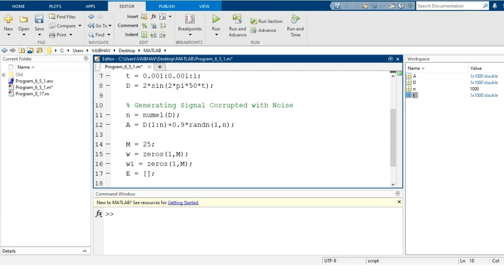And as we have seen the update equation of the LMS algorithm, it has on the RHS the second term there, one constant that is called mu, which is representing the step size here. So here we can keep, for convergence purpose, the value of this step size to be very, very small. So we have 0.0005 as the value of mu here. So this is for convergence of the LMS algorithm here.